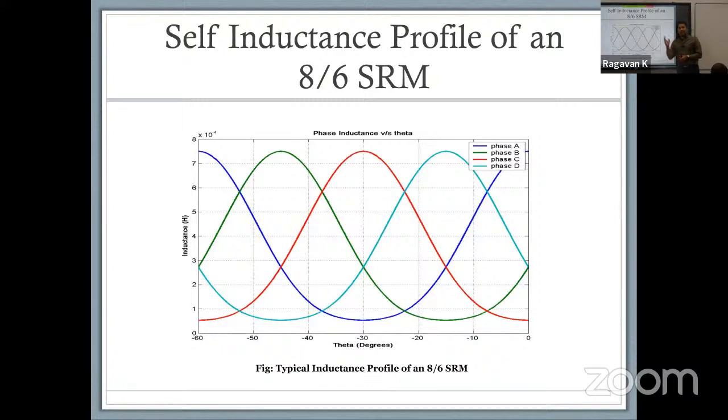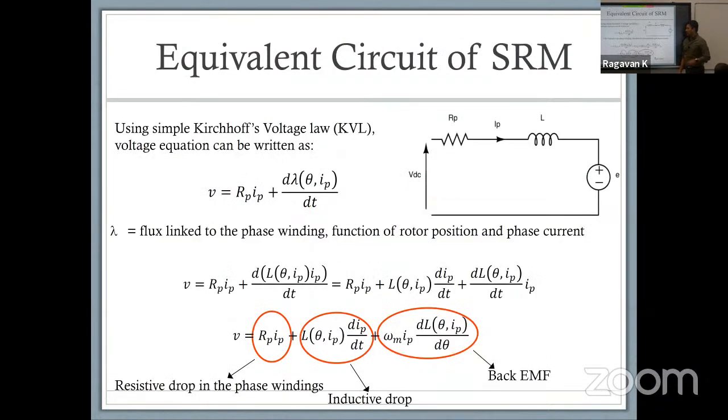What you see here is that as the rotor moves from one point to the other, each one of the phases has an alignment that happens before the entire cycle is over. So let's say this phase here, phase C, is our initial phase of reference because it's in the middle of the screen, it's just easy to point to. But there is a phase right before that, and there is a phase right after that that actually has an overlapping inductance, which is, if you apply current here, you can have a direct effect. If you apply current here, it'll have a completely different effect. Like I said, you have phases nearby that can be energized, which can lead to negative torque. How that happens, we will talk about in just a little bit.